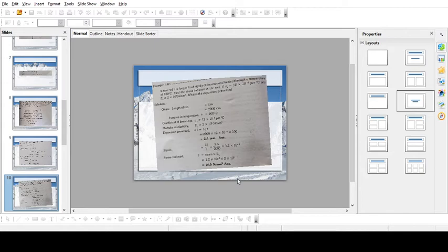Now also the free length of the bar, or the length by which it is decreasing or increasing, is delta L1. So it is simply L alpha 1 T. Similarly, for the second specimen also, delta L2 is equal to L alpha 2 T. Now, if alpha 2 is greater than alpha 1, then you can see in diagram B that it will expand like anything.